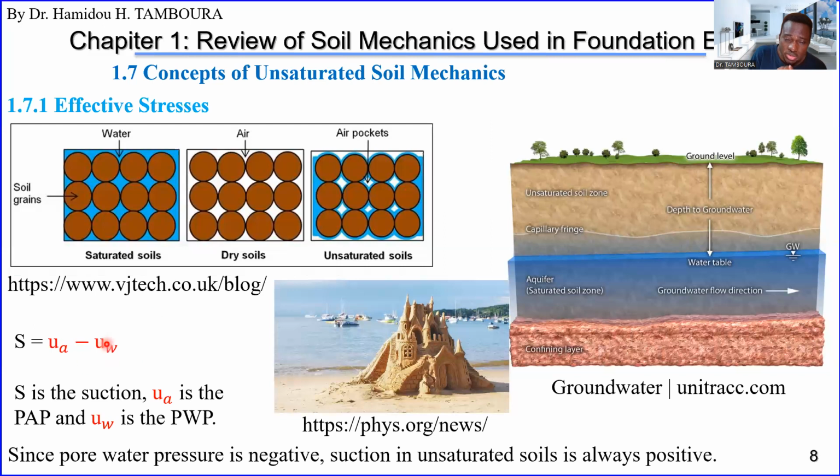And this suction is somehow a force that is pulling the soil grains together. They hold them together. This force of suction is the reason why you can build this kind of castle on a beach, for example. See, this sand is not saturated, it's unsaturated soil.